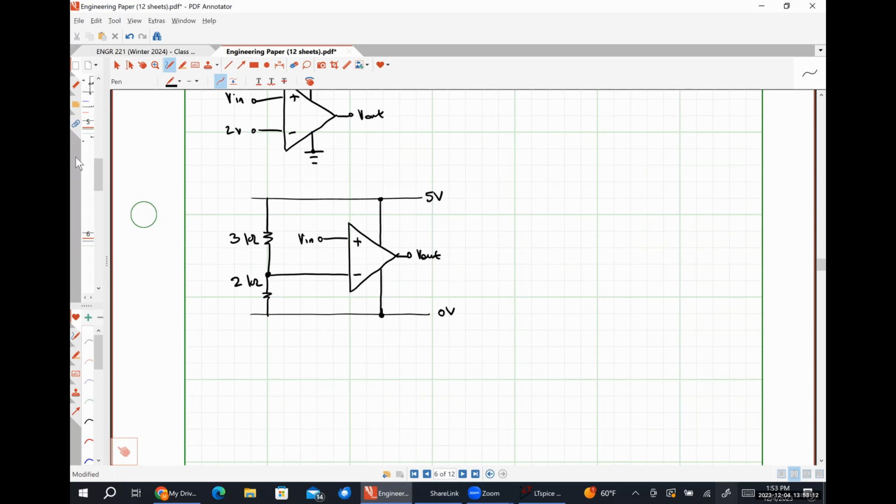I was just explaining about this. Yeah, so I was expecting you guys to Google it and all that kind of stuff, but it's fine. So when there are 3 resistances and they're equal to each other, to go from this delta configuration to a Y configuration, you simply divide the resistor value by 3. So that's why these 10s look like 10/3. So effectively what I'm doing is I've subdivided this network in between these terminals X, Y, and Z, and I'm replacing it with an electrically equivalent network between X, Y, and Z. And then you get this.